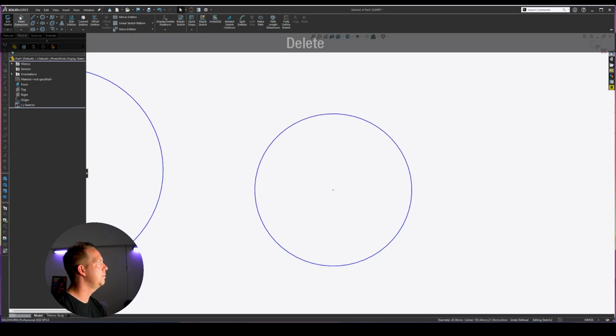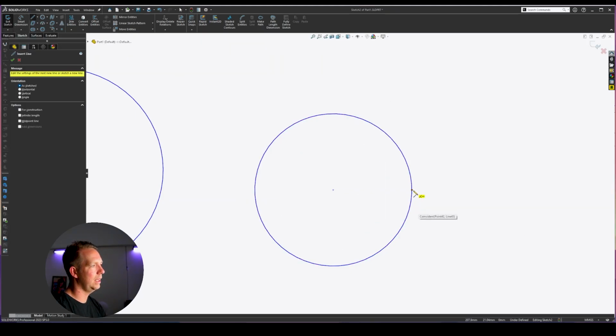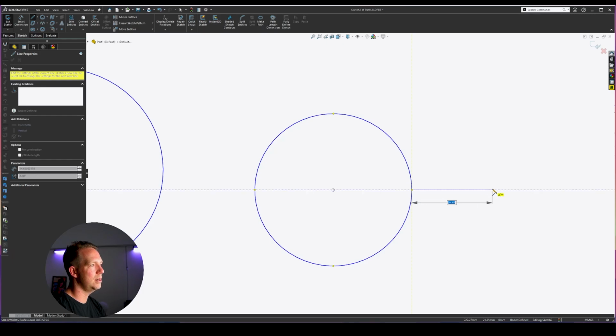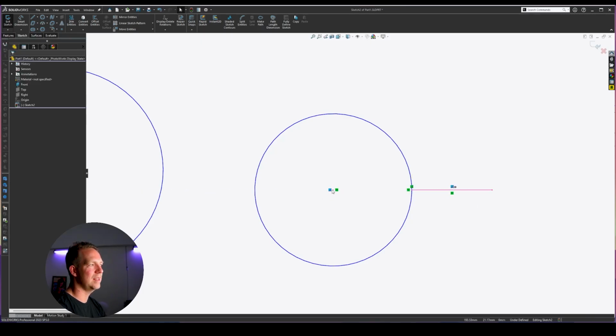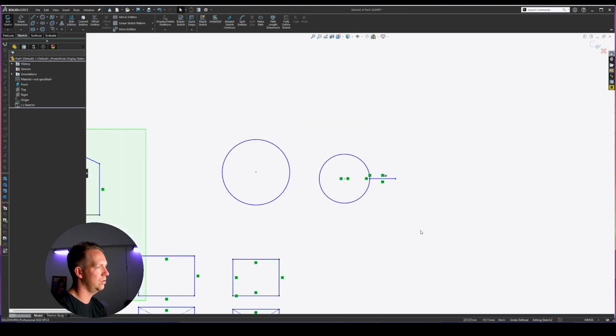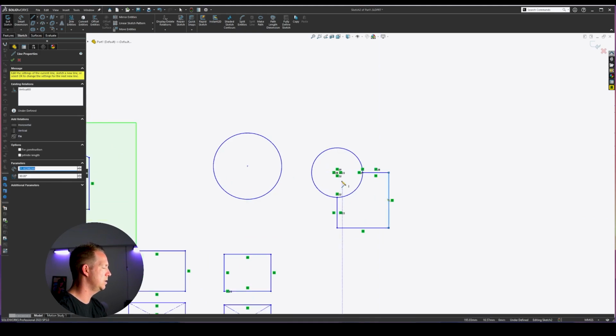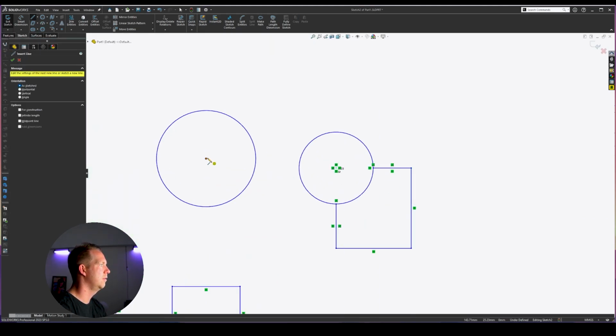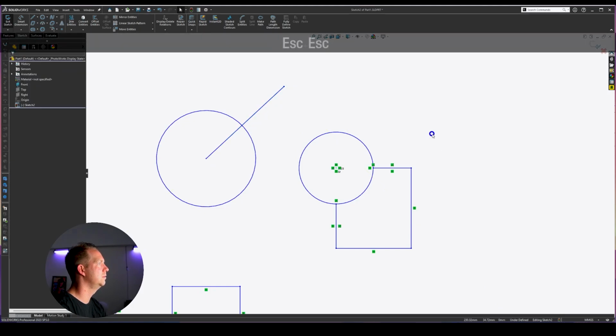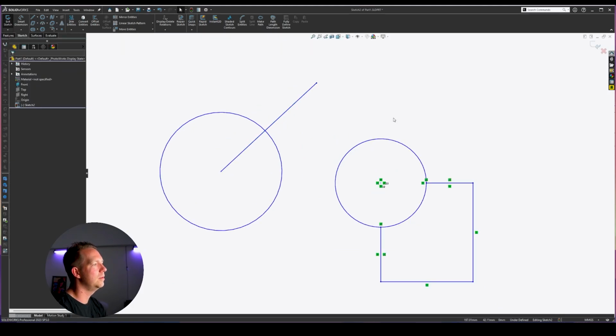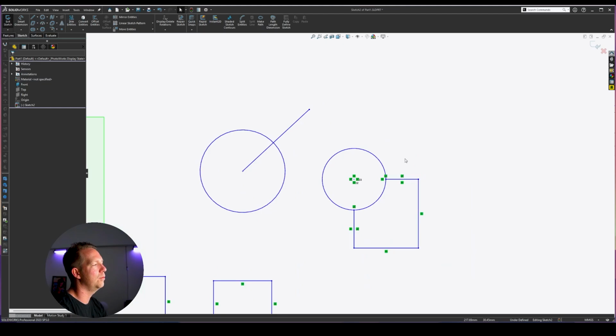To clarify, let me try a line tool, and when I click from this point here and draw a horizontal line, it's added a coincident relation to the center point of the circle, and it's made the starting point of that line horizontal to the center point. Again, this is to do with the relations. We'll talk more about that soon. So you can draw lines off a circle like such, or you can also draw a line from the midpoint of the circle. So the circle, very easy tool, but very flexible when you combine that with trim tools. We'll explain about that shortly.